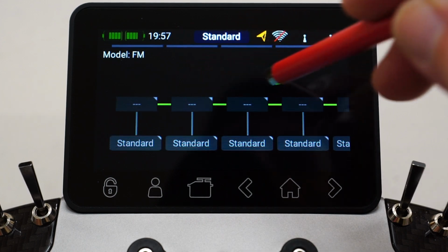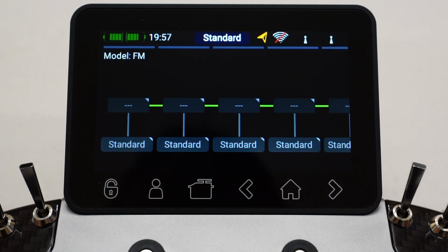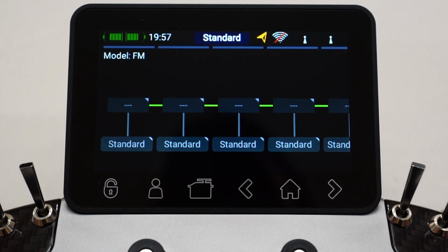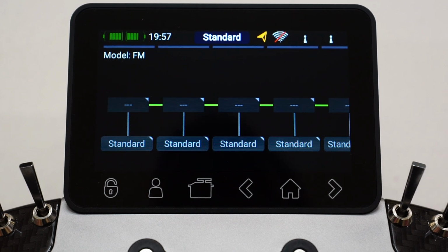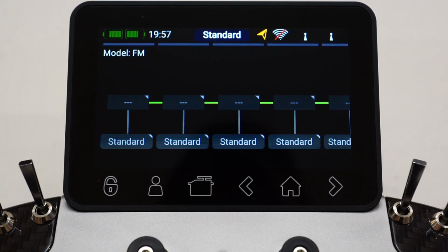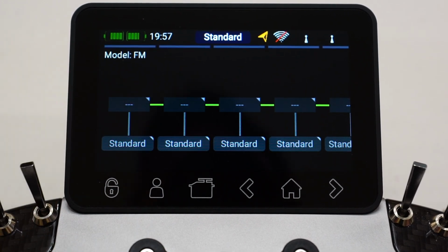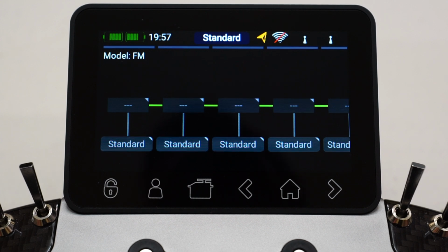So typically in a lot of my settings, or a lot of my aircraft, my first flight mode or the highest priority might be one where I kill the engine, for instance, for a particular reason. Or I might have the model in a particular safety situation where you can't operate the throttle, the motor's locked out, especially with my internal combustion engines. So you'll notice a lot of my models, the highest priority flight mode is basically an engine kill situation. And I'll have the model in a particular setup configuration where it's totally safe.